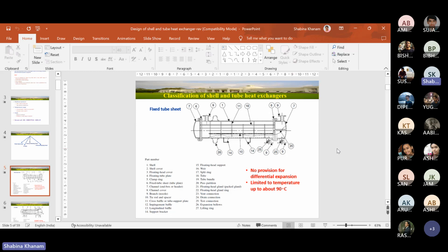Okay, I hope you are getting my point. Partition plate is available where fluid of tube fluid is entering. Okay, only in this plate is not available in this bundle. So why are we considering that in bundle diameter? Because when I'm having this partition plate, it divides the number of tubes into either the above section or below section, but not here. If you see this partition plate, aligned to that there is no tube in this side.